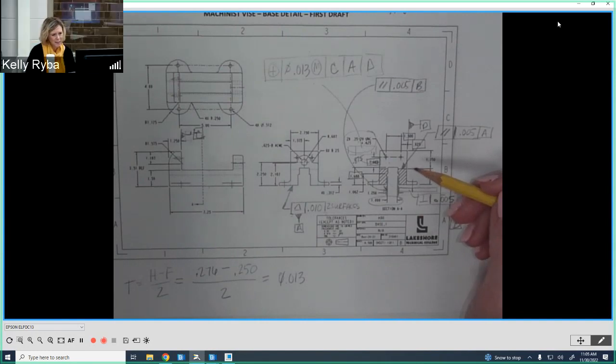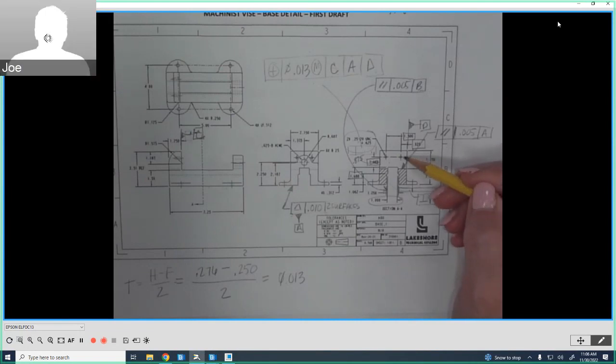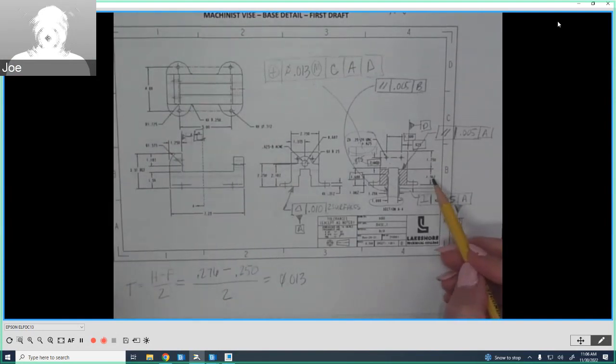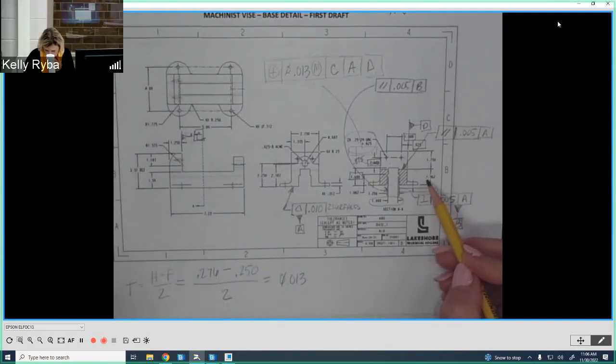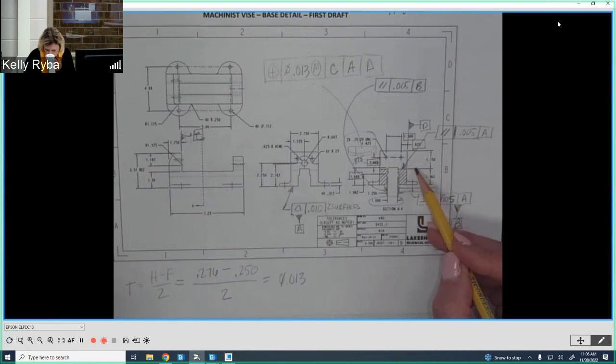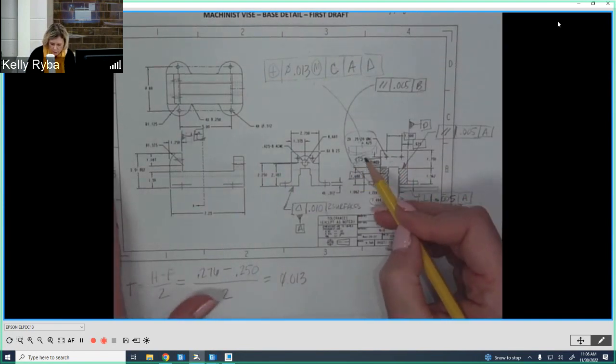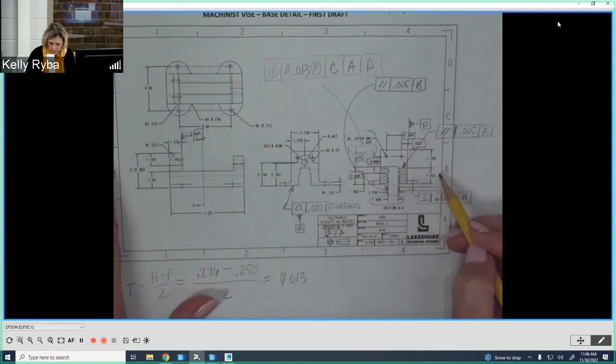You know what? It could be either or, honestly. But then the basic dimensions wouldn't work then, right? Because it wouldn't chain back. Then we'd have to use this one over here. If you went from here, the 1 inch, and then down. So, like I said, it's either one or the other. It's totally up to you. If you want to do the 7/8, then go on this side. If you want to do the 1 inch, then you have to include this one. Okay.